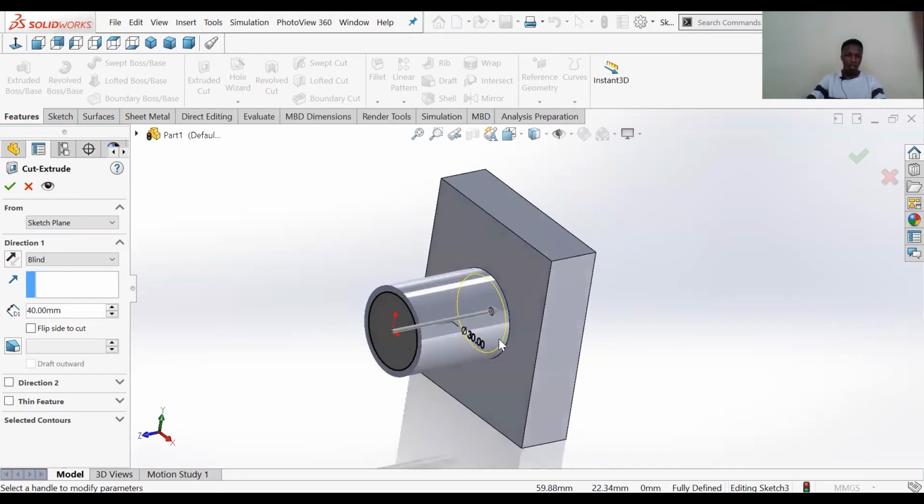of the shape by which we are going to remove our material, see. Now, under the PropertyManager on your left side, under the Cut-Extrude option, you are given several options as well, not too different from the ones for the Extruded Boss tool. Here you are going to select From. Remember, you can select from a surface, from this surface here. But we are going to be using just From Sketch, from where we have drawn a previous sketch.